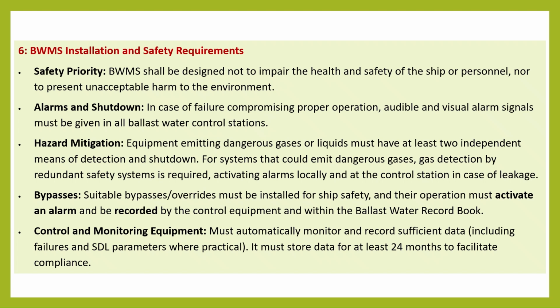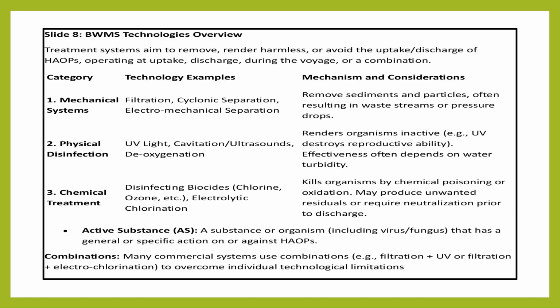BWMS installation and safety requirements. Safety priority. BWMS shall be designed not to impair the health and safety of the ship or personnel, nor to present unacceptable harm to the environment. Alarms and shutdown. In case of failure compromising proper operation, audible and visual alarm signals must be given in all ballast water control stations. Hazard mitigation.